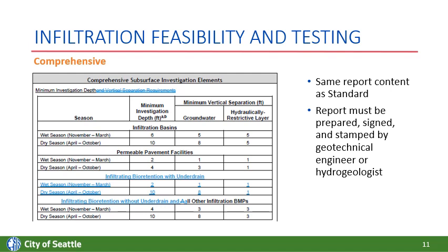And this is for the comprehensive subsurface investigation. So this is going to include projects with significant amounts of impervious surface that are going to be infiltrated on site. Again, referring to that table 3.1 for the different requirements for subsurface investigation for your project.